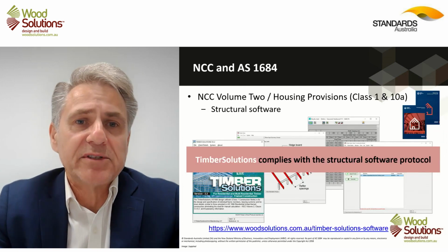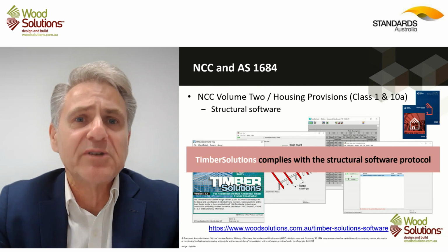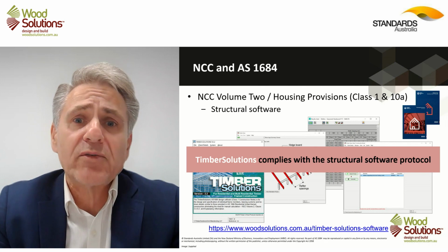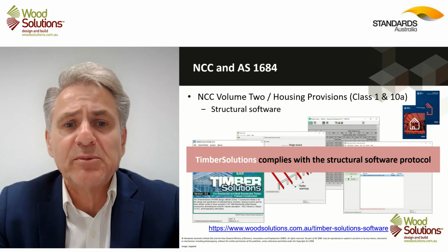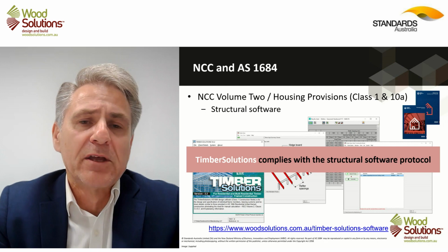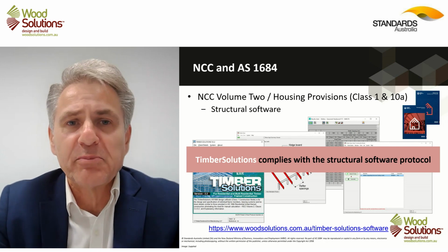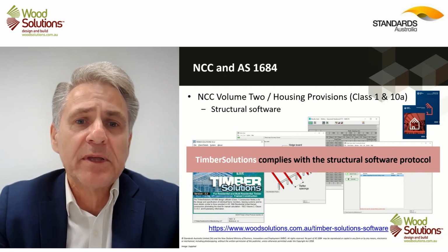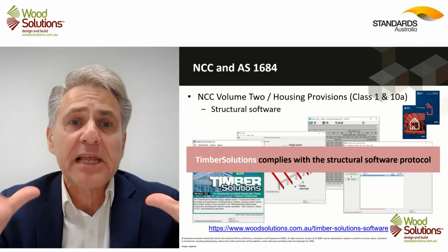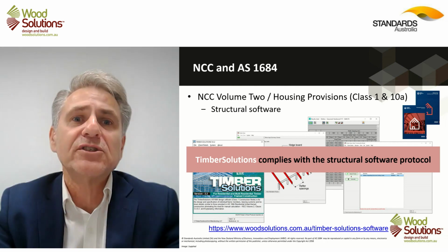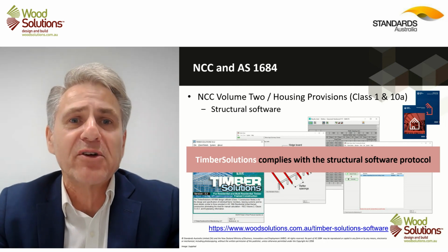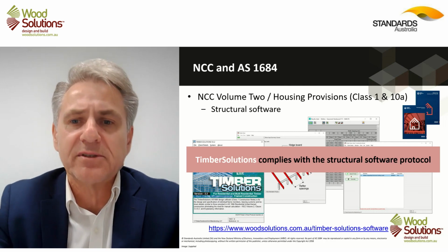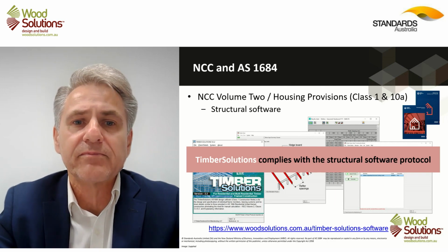And the key thing, I suppose, out of this, the reason for bringing this up, is that there is software out there from a span table perspective. There are proprietary products. This is a free software that can be downloaded through Wood Solutions. Basically, the engine in this software package was used to generate all the span tables in AS 1684. So this particular software package is a black box version within the bounds of the ABCB's software protocol. So you can use the software in compliance with the requirements of the National Construction Code.